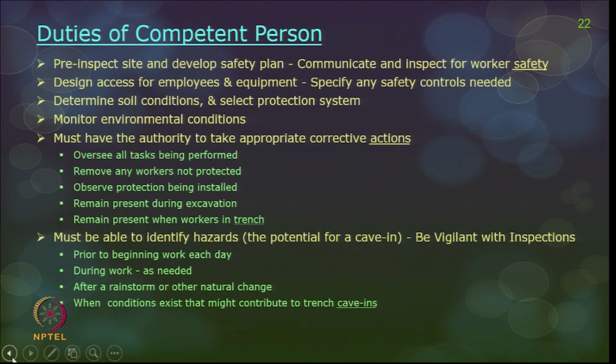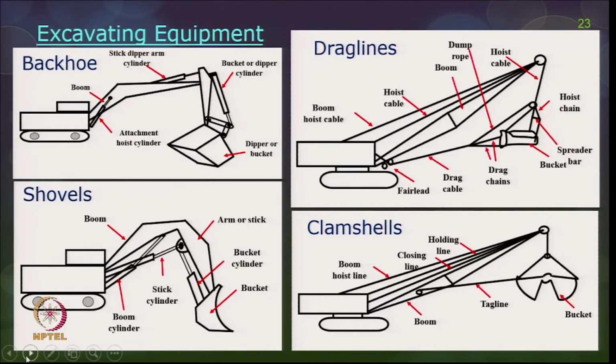Okay. And these people also should be able to identify hazards, which implies the potential for a possible cave-in, and they have to be vigilant with all inspections also. So, prior to beginning the work each day, during the work as needed, and after a rainstorm or any other natural calamity which has happened, and any conditions exist which might lead to a cave-in happening.